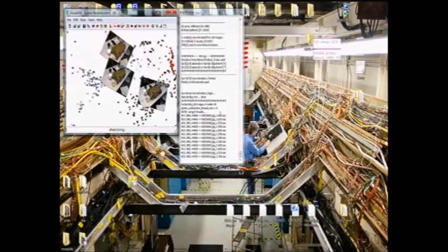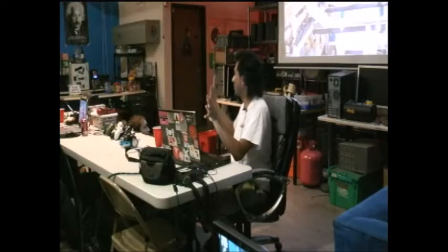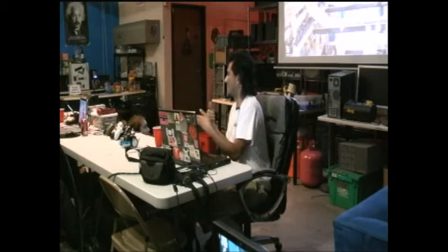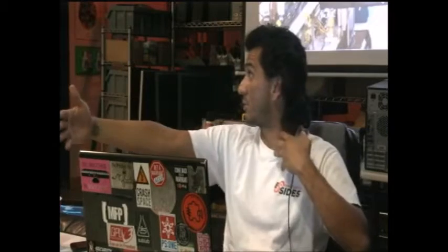First, it's going to run an algorithm to undistort each one of these images so it can accurately reconstruct the dense point cloud. This process, like I was mentioning earlier, is very dependent on optical properties. So your lens properties are pretty important to getting your results. This does not work very well with fisheye lenses because that distorts straight edges. You want lenses that most closely represent the human eye, something between a 35 to 50 millimeter lens. Telephoto lenses work really well just because there's almost zero distortion.